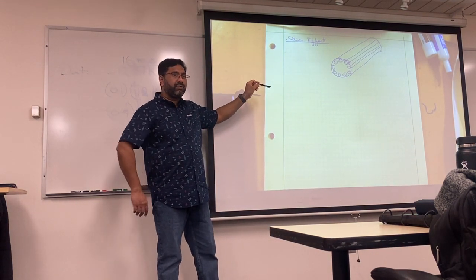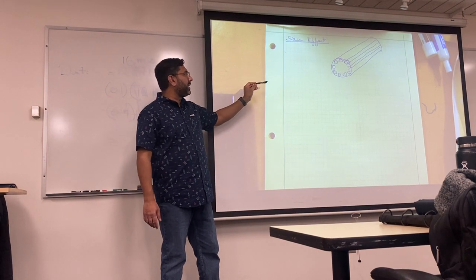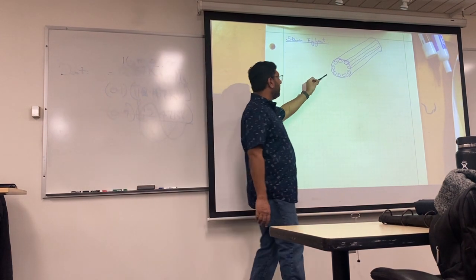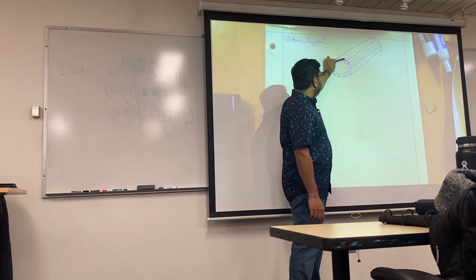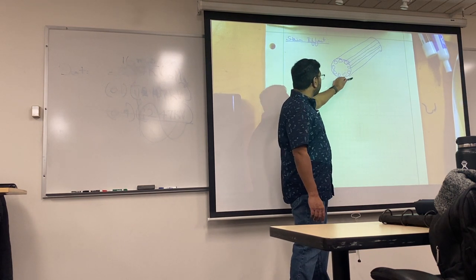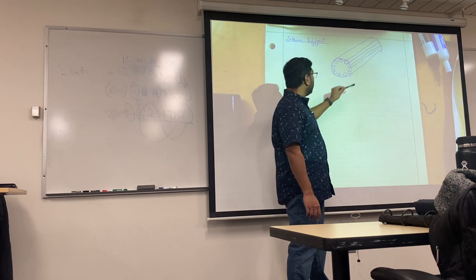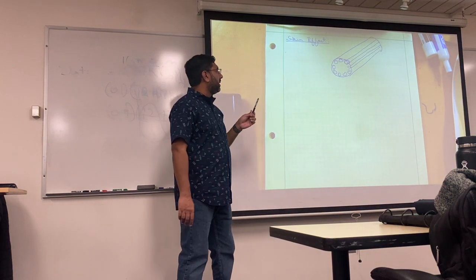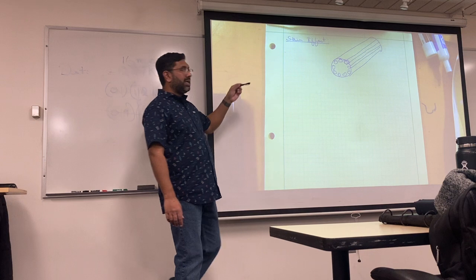This is also a reason why we try to do high voltage DC, because with high voltage DC, I can pretty much use the entire cross-section here. AC on the other hand is trying to push itself and occupy only the outside. Now with harmonics, the other issue is it has multiple frequencies.